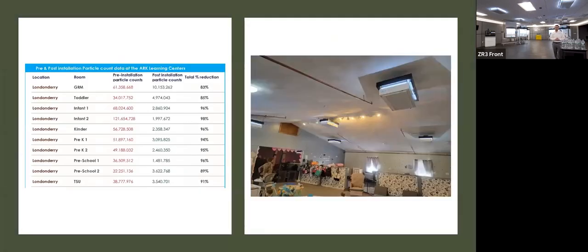And then we did a Head Start. So this is, I think, the infant room in the Head Start. They have 3 centers, and this typically isn't our space, right? We're typically in labs. So again, a learning experience for us. We went in, we wanted to assess the air quality, the space. And you can see when we did pre-installation validation and particle counts, how dirty the air was, in red. You're looking at some very high numbers, and these are cumulative readings, but the majority of these readings are at 0.3 micron. And we look specifically at the infant room, which you see here in the picture.